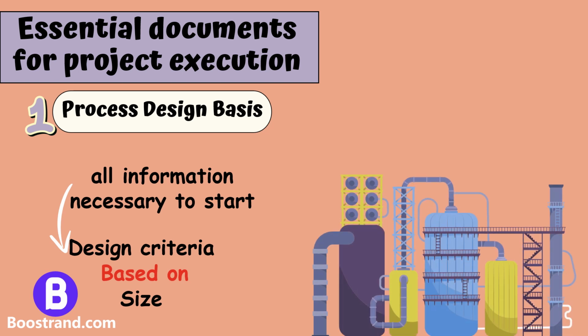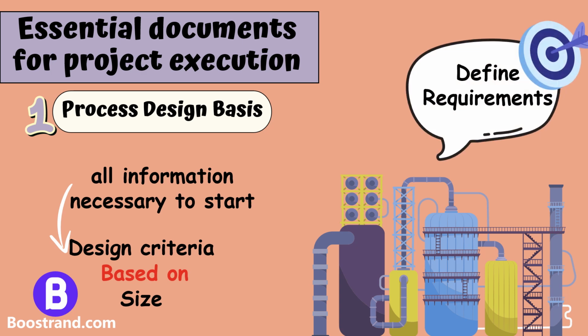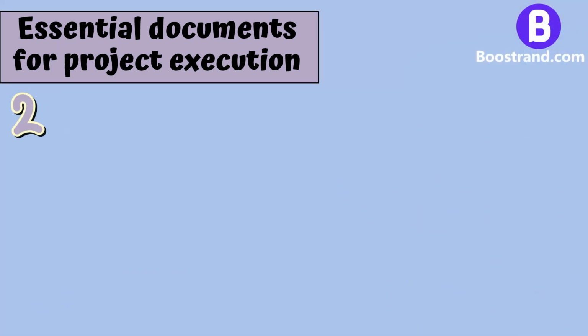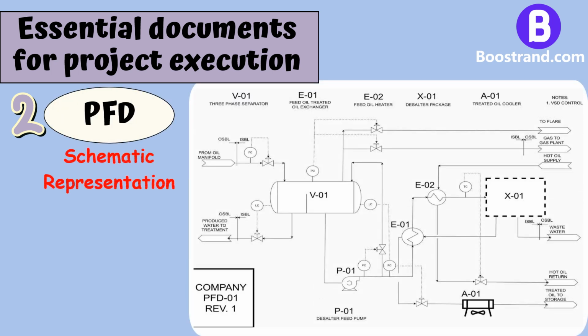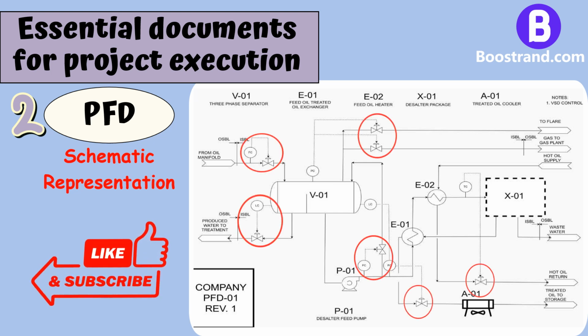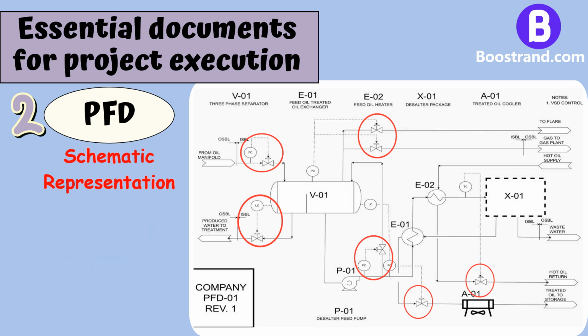So here, we see that the basis of design is highly important to define what is exactly required in the project. Secondly, process flow diagram, PFD. A PFD also shows all equipment, lines and control loops in addition to normally no flow lines that are not shown in process simulation. For example, relieving lines to flare that are used to control pressure, tank blanketing, and other things. A PFD is also expected to highlight all operating modes.